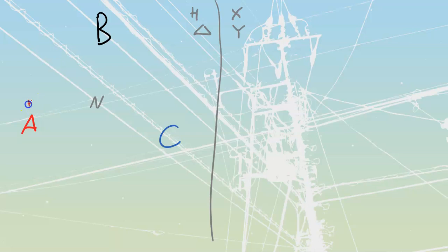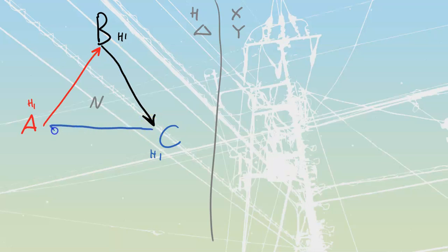We always have an H1 of the associated phase that is going to be on each one of these connections, our A phase, B phase, and our C phase. So we've got our H1 over there, and then we just connect the dots. Remember that the 1s are the tails and the 2s are going to be the heads of these vectors. So we're going to start down here, and I'm going to draw that arrowhead in. Remember that these arrowheads are really important to us. The B phase, same deal, and the C phase, same deal over here.